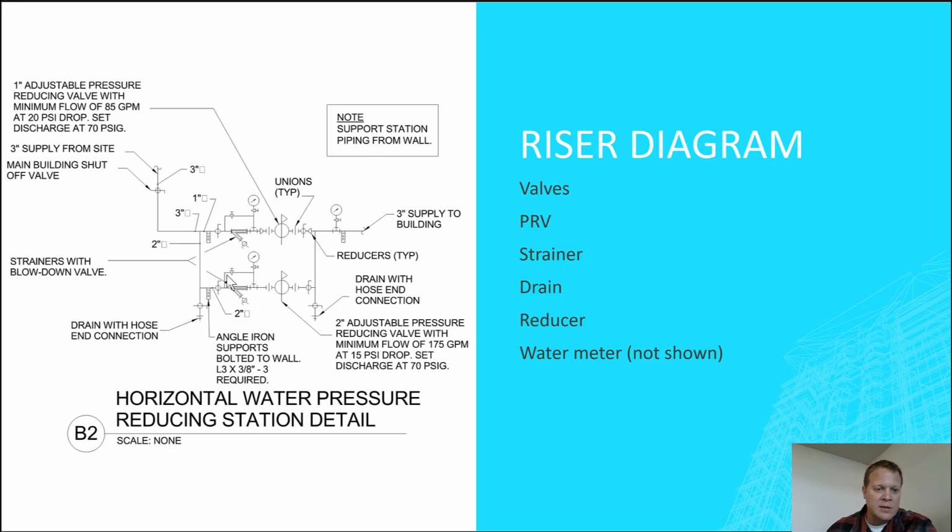What's that? Well, it's a little bypass with some valves and a pressure gauge. What you can do is, this is the strainer right here. So the strainer is picking up any debris in the water. And if the strainer is getting full of debris, you can check to see if the pressure going this way is different than if you isolated it and let it go that way, and you'll be able to tell if your strainer's got problems. Anyways, the strainer is pretty cool. We can look at that later.